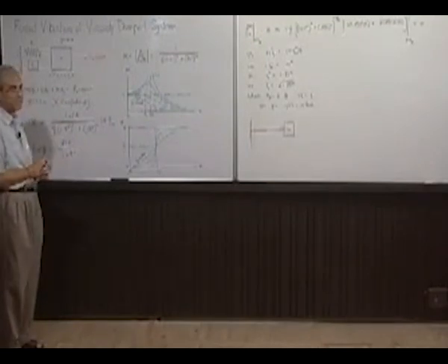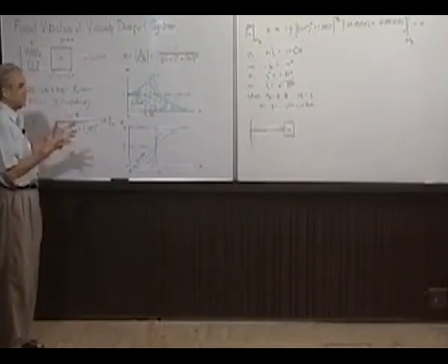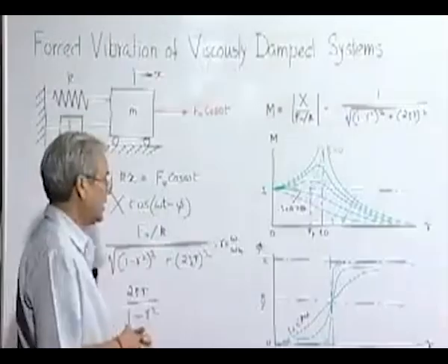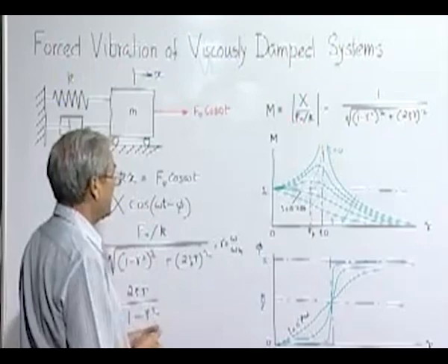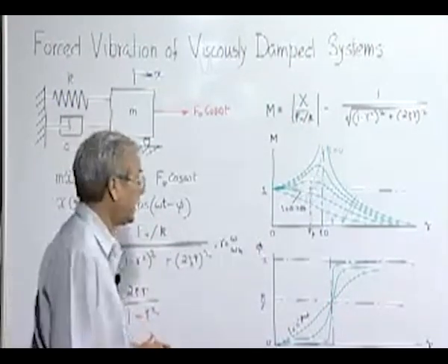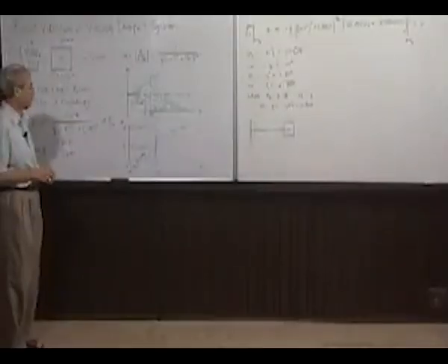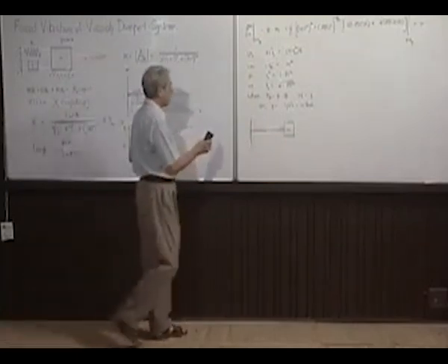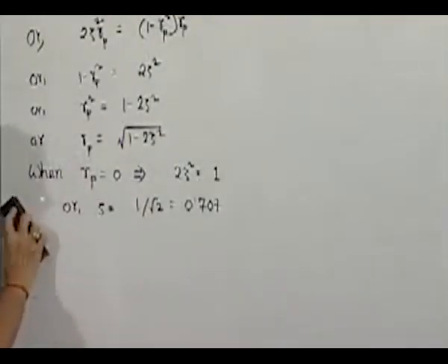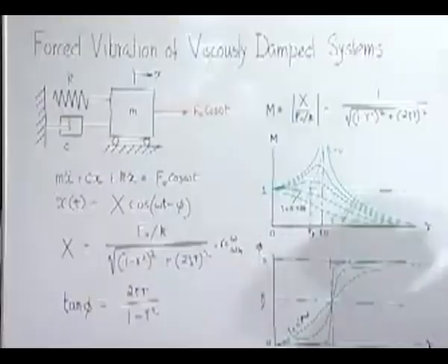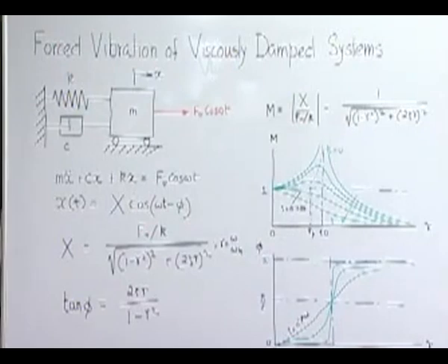of systems very effectively, where the system can be made much lighter compared to what it would have been if the load is static. But nevertheless, we should keep in mind that the natural frequency of the system has to be designed in such a manner that R becomes much higher than 1. There is another way of solving this problem which I will take up. The reason being that it can be not only remembered much more easily, but can be effectively utilized in more complex situations, which I will demonstrate.